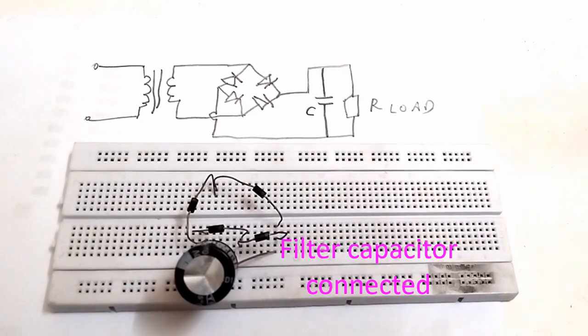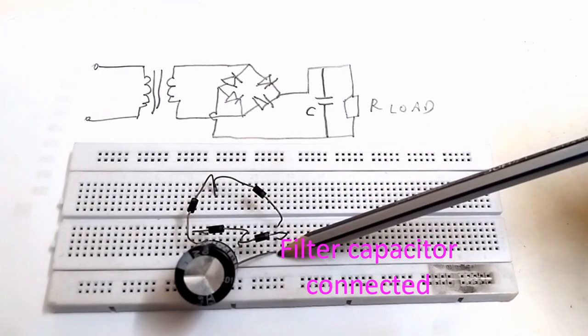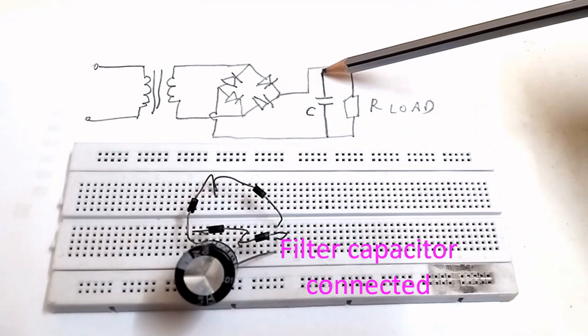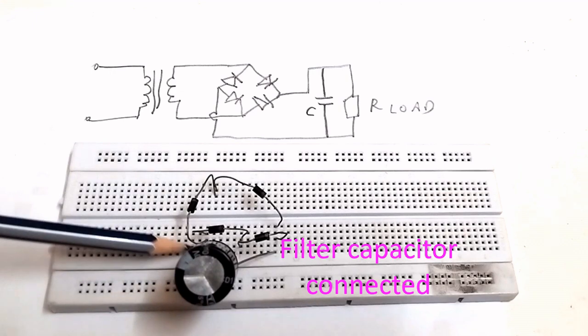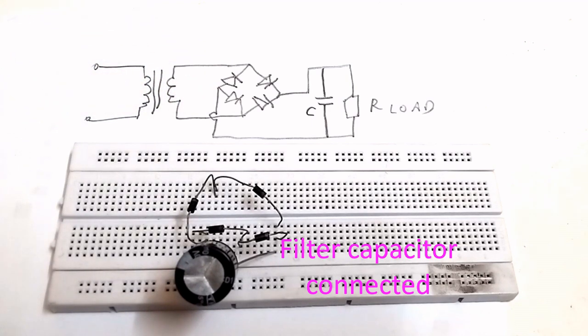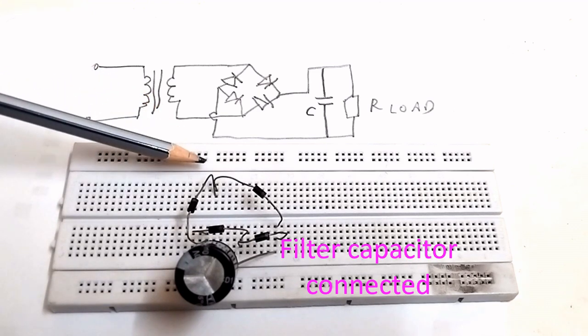Now I have placed the capacitor in such a way that the positive pole is here. This will correspond to this region because it's in the same line, in the same row. You can see that it will be here. It is the same as this connection over there in the circuit. Then you have the negative pole connected here, which is the same as here, and will correspond to this region. So I have completed the bridge. Now what remains is I have to connect the transformer from these 2 points.